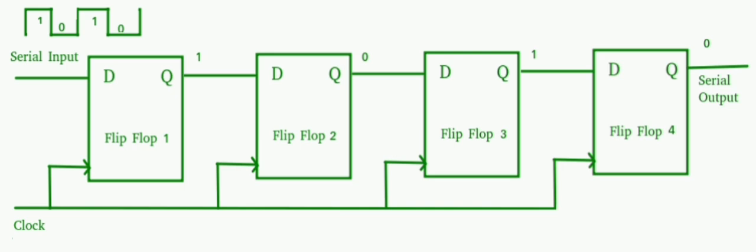4-bit left shift SISO register. In this SISO register, the MSB data is applied to the LSB flip-flop, the D flip-flop. To enter the n-bit data in serial form, we require n clock pulses. To exit, or get the output of n-bit data serially, we require n-1 clock pulses.